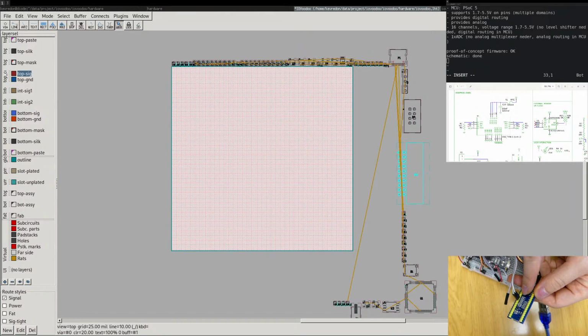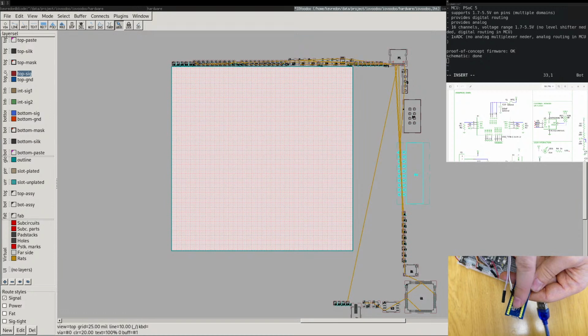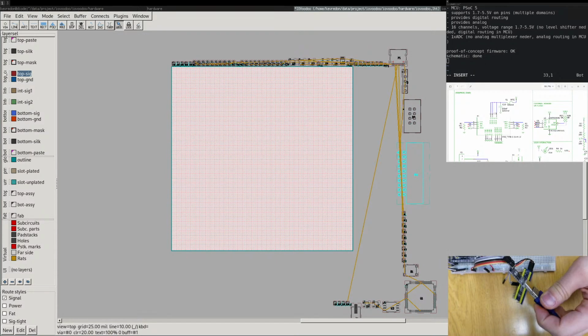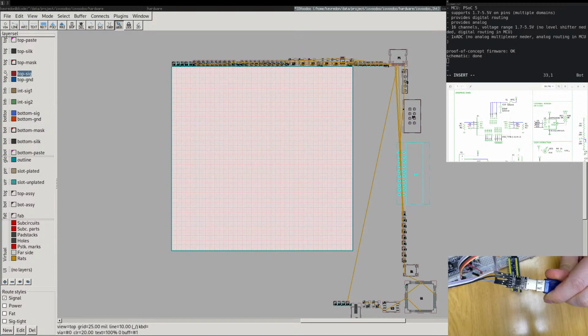And because these are small components, the solder on them, although it will melt again, not completely but mostly, it will hold the component in place. If the components are too large and the solder wouldn't hold the component in place, you have to add some glue, and this costs money. So passing the board 2 times in the reflow oven costs money, adding glue onto the component costs money, so double-sided devices cost more money. So this is why whenever you can, you do something which is single-sided load, where all the components are on one side. Here, nothing is on the other side. No component is on the other side.